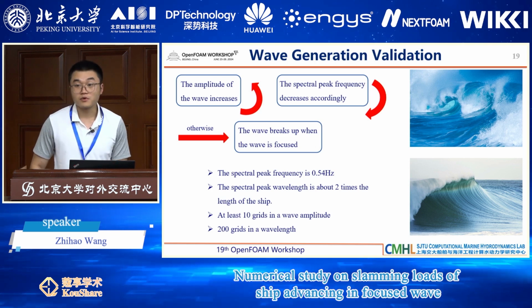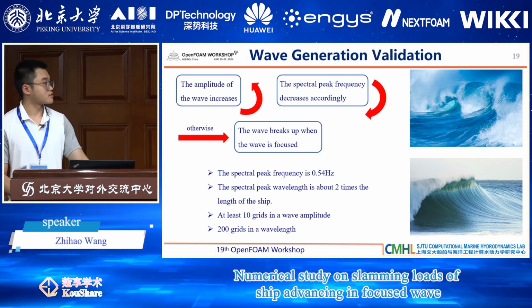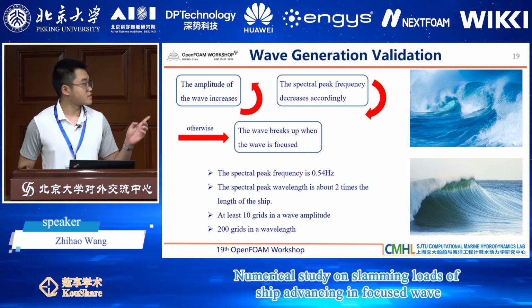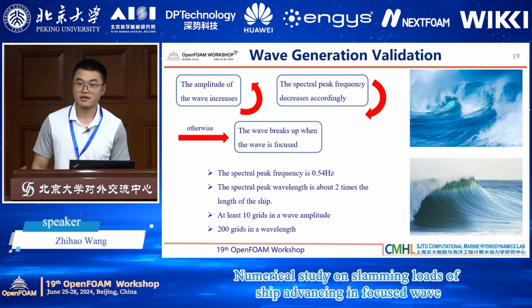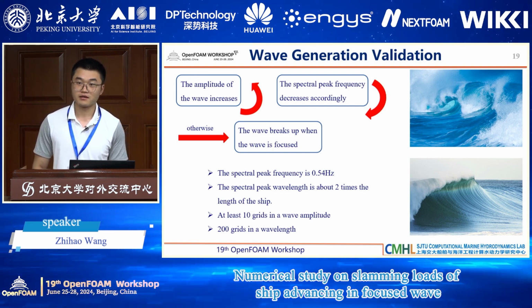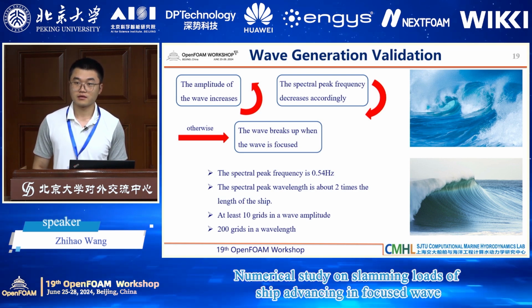It's a JONSWAP spectrum. Yeah, and the frequency is... I've tried a lot of frequencies, and this frequency shows better results. Other frequencies may cause the wave to break. Okay, so you want to make sure your wave is not breaking. Yeah.